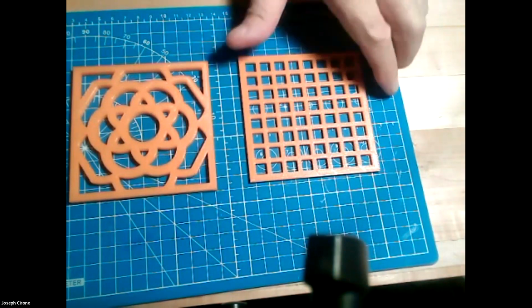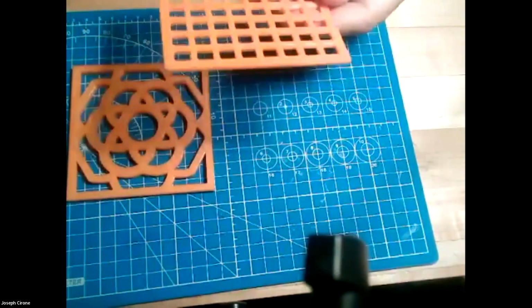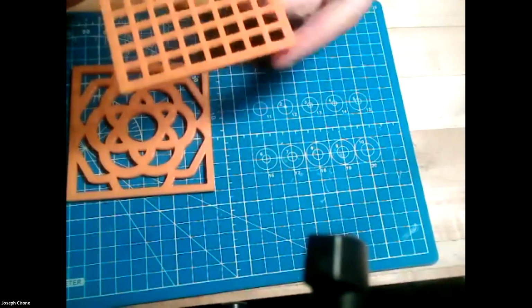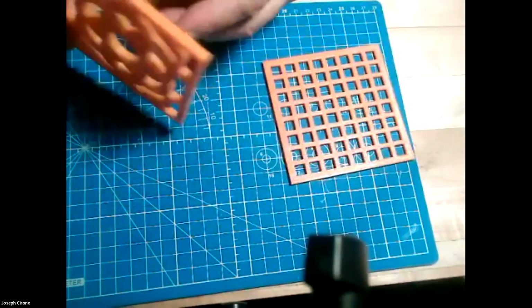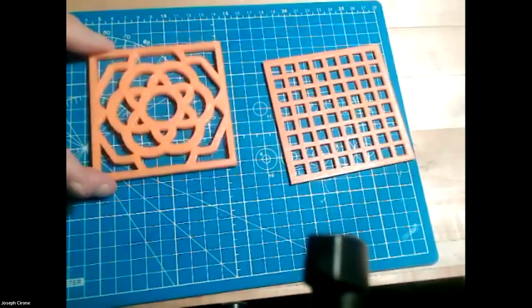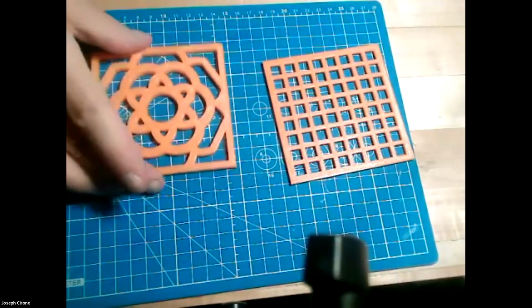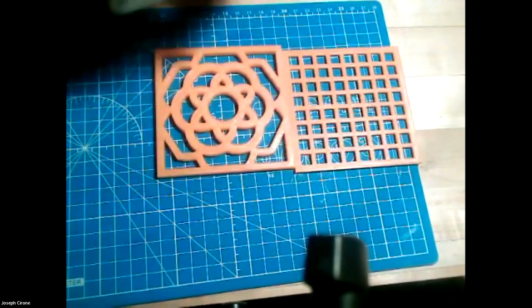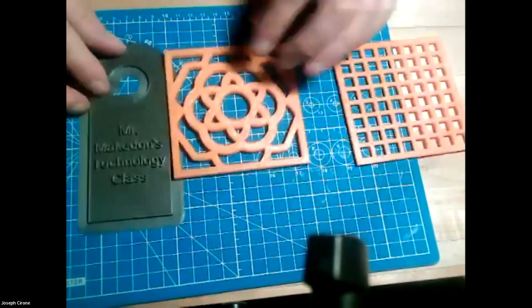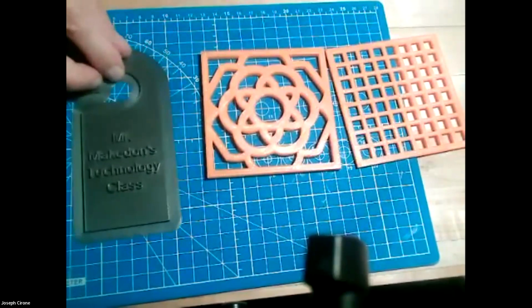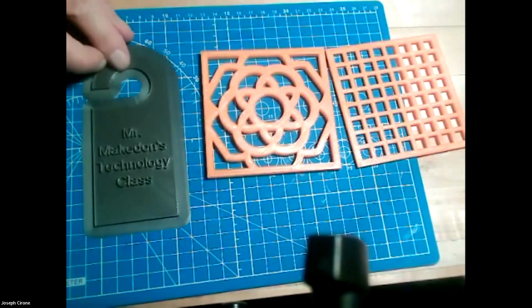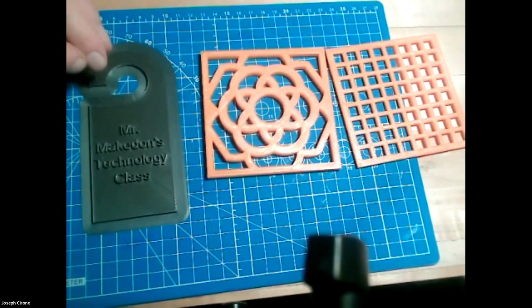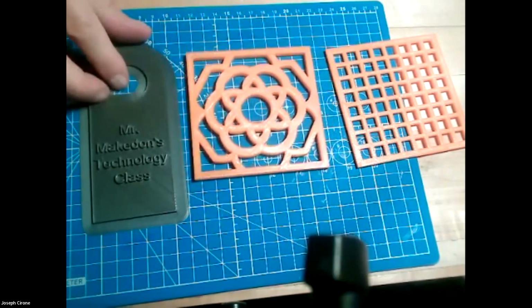And so here's an example of what the projects will look like once we're done. Now, I did not put a brim or any build plate adhesion on this, and this one worked pretty good. Sometimes what will happen is the parts will kind of lift off or have some difficulty. And so as we're working with designing for 3D printing, we're looking at how the parts are adhered to the build plate, and we're using basic extrusion techniques for 3D modeling.